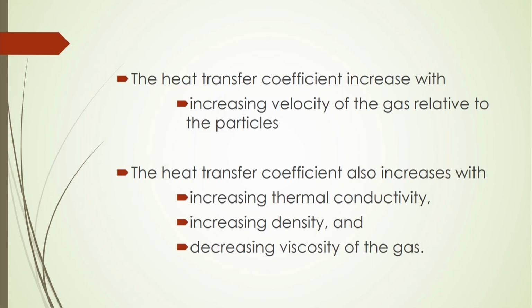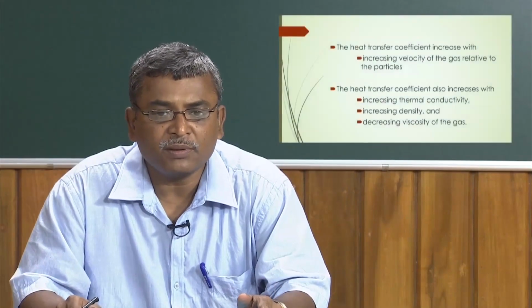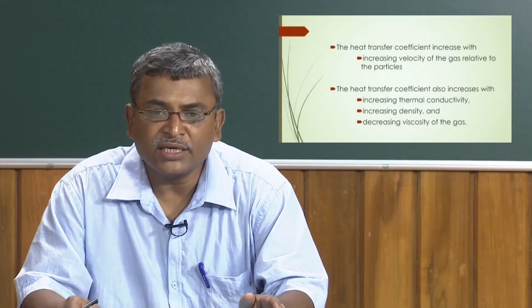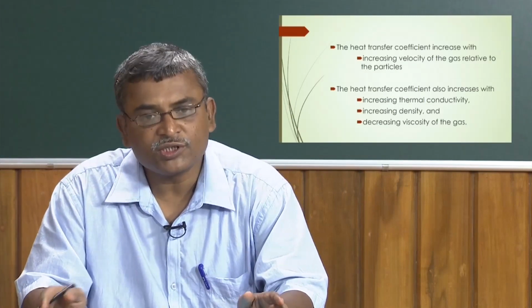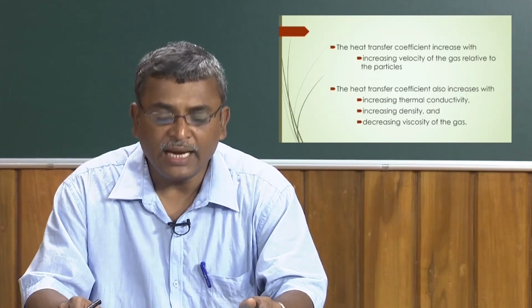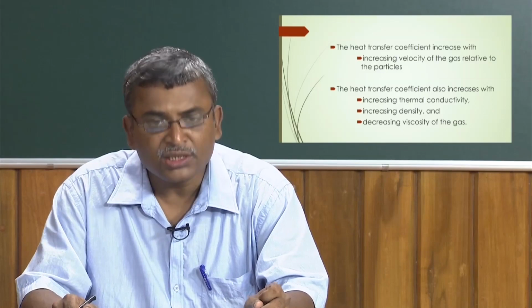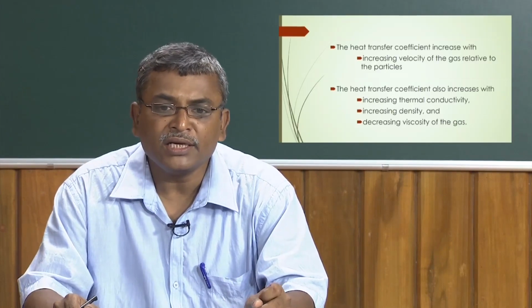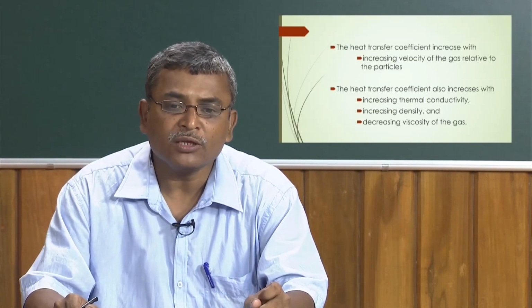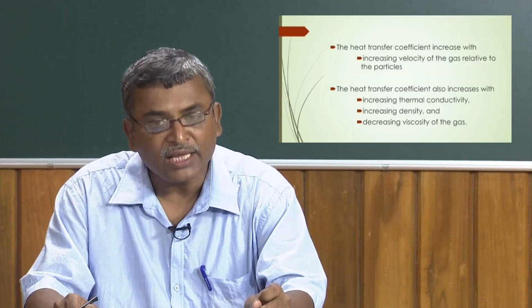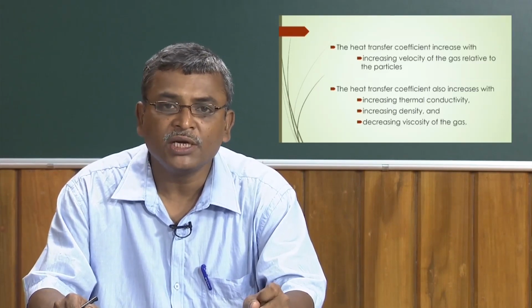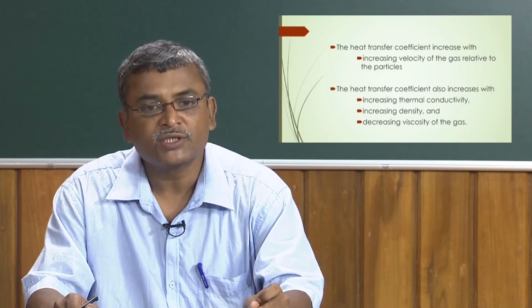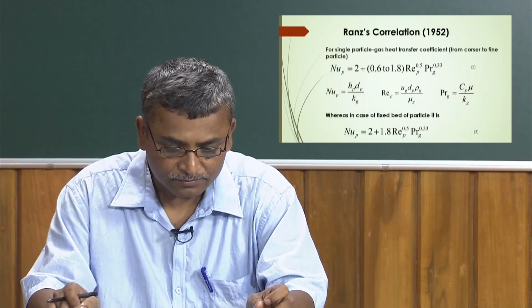Also, this heat transfer coefficient will increase with thermal conductivity, that means the physical properties of the system, the physical properties of the particle, even particle density, even viscosity of the gas. You will see that the heat transfer coefficient will increase with thermal conductivity and increase with density, and it is very interesting that it will decrease with the viscosity of the fluid.